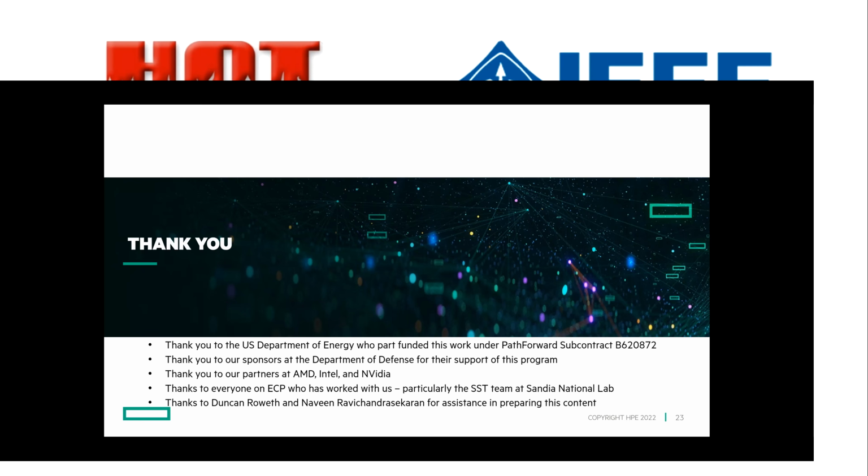Okay, next question is from Manju. Is remote flush tied to any particular memory bus or interoperable? So the Cassini connects to PCI Express, and so a flushing operation on PCI Express is simply a 0-byte read, and so the transport will let us communicate the need to do that, and so that works with anything that honors the PCIe ordering semantics for a 0-byte read.